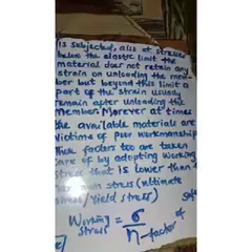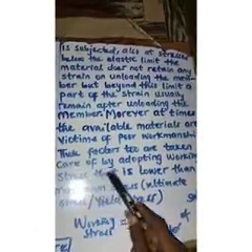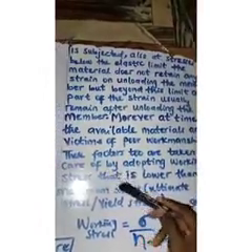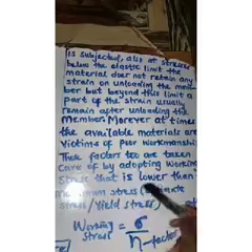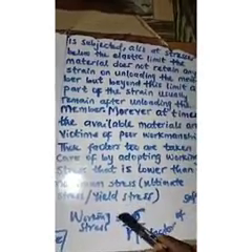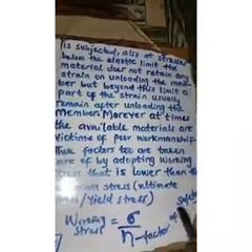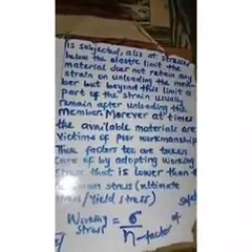These factors too are taken care of by adopting a working stress that is lower than the maximum stress. The maximum stress is also known as ultimate stress or yield stress, and working stress is equal to this stress over the factor of safety. Do jot all this down.